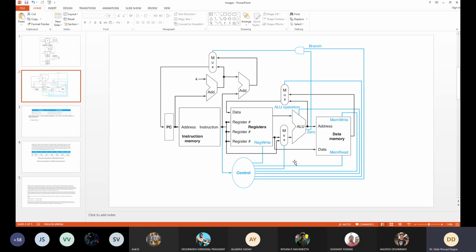Next you can see that this multiplexer, I need to give the port numbers here. So 0 will go from register, 1 will come from here. Okay, let's assume that the line is 0. So if this signal name is multiplexer ALU, let's assume that this is multiplexer ALU. Okay, so multiplexer ALU signal, I can give mux ALU equals to 0. 0 means this one will be taken.